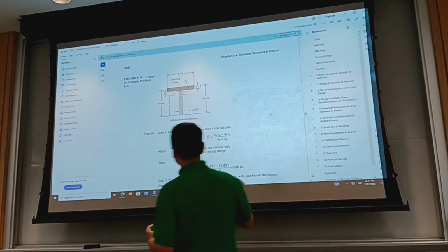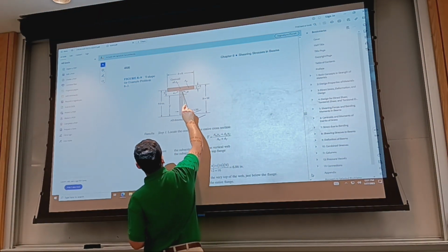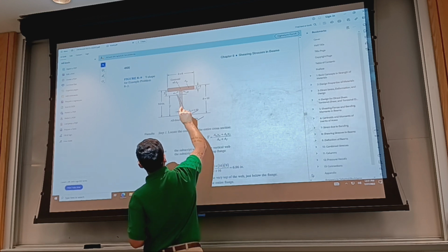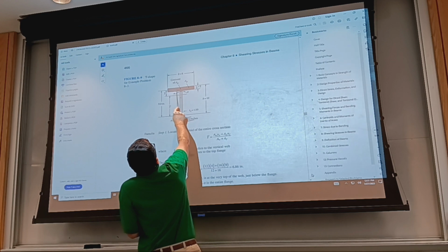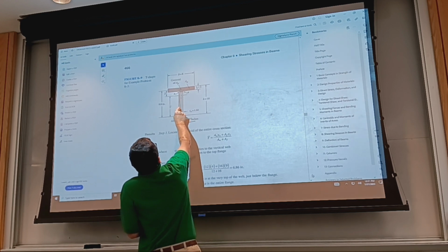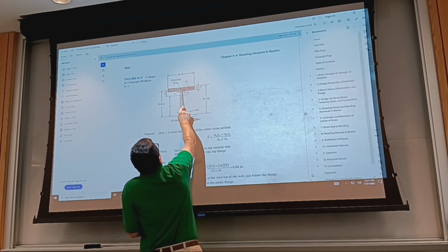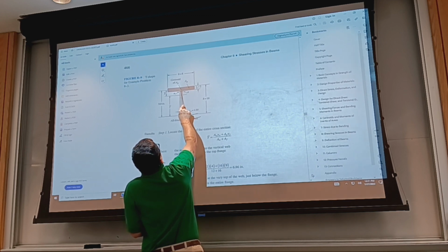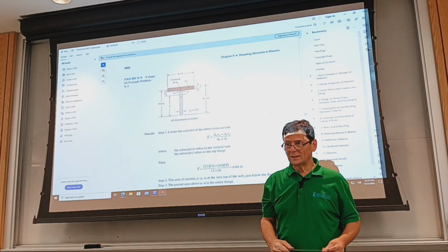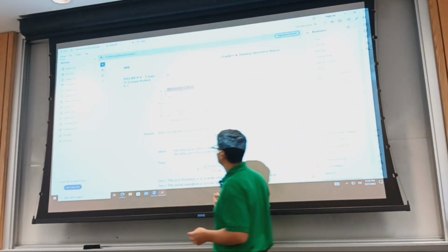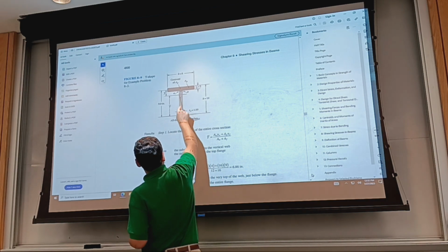You get the same value Q if you consider instead the lower. So I can find the centroid of a rectangle. This one here, it appears that they meant to say extending this all the way. I'm seeing it slightly below. Yeah, that's my question. Yeah, this should be slightly below the neutral axis of the horizontal portion of the T. But yeah, you can work with the other portion.